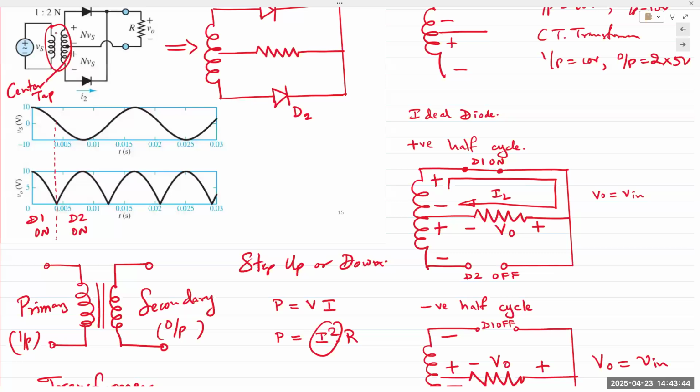So if you want a 5-volt output, then we have to add in every single diode voltage drop for every single half cycle. So in a half wave rectifier, it would be 5.6. In this full wave center tap will also be 5.6. So it would step down from 110 volts to 5.6 volts. If you are just talking about the diodes, then there's another explanation of the other additional components, and we'll talk a little bit more in depth. But the answer is, yeah, if you want to account for the diode drop, the transformer is going to step it down and then account for the diode drop. So circuit designers will actually do that. Yes.